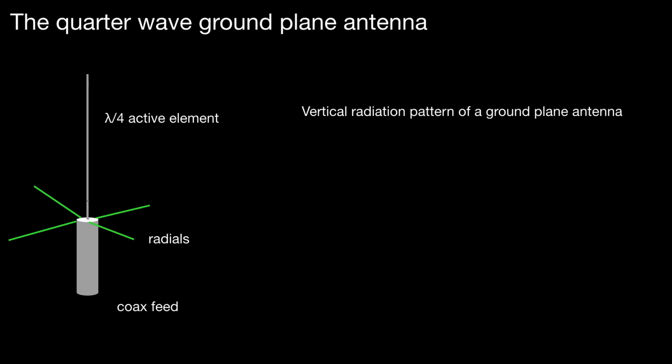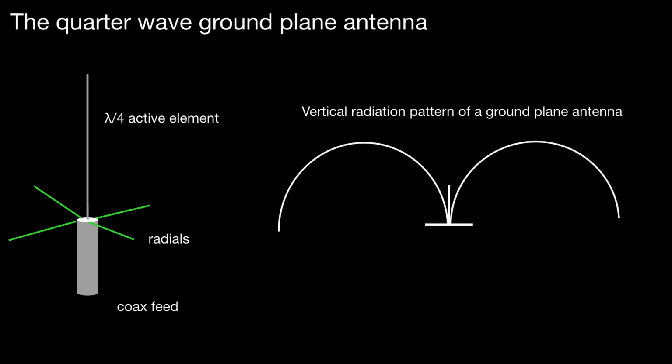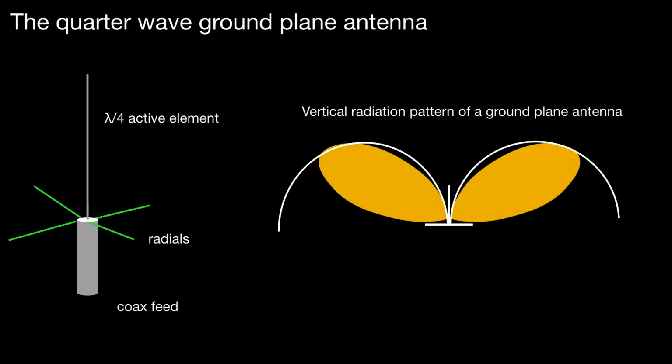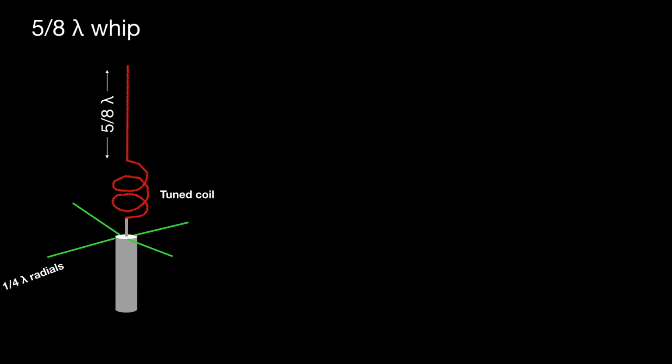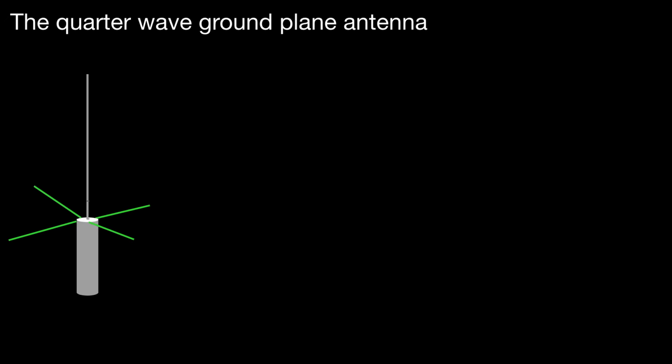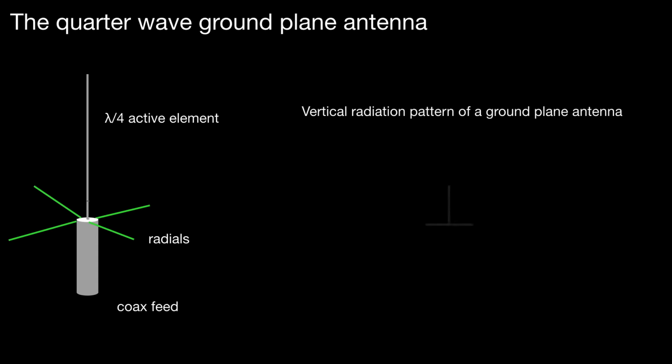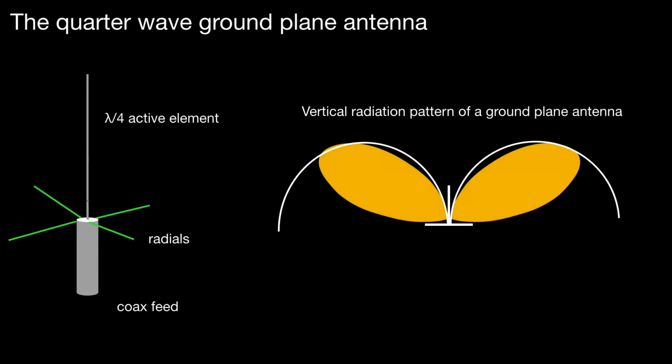The vertical radiation pattern of a ground plane antenna would look something like that, ideally, if you imagine it, but actually the modification of the ground then establishes two lobes, and once again we have direction of maximum radiation there. Going back to that one, the horizontal pattern, by the way, is simply a circle. As you might imagine, in the horizontal plane, it's an omnidirectional antenna.